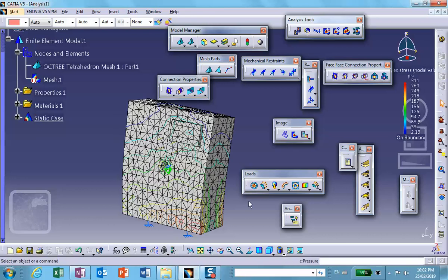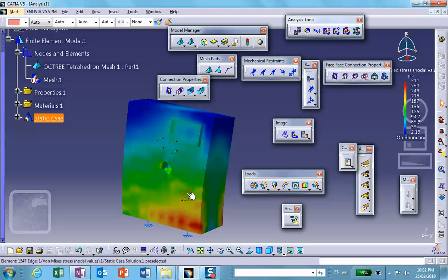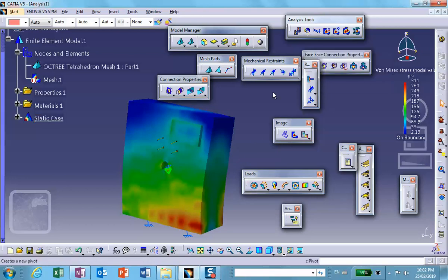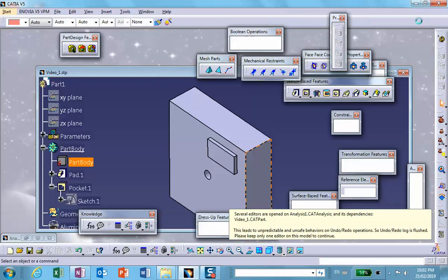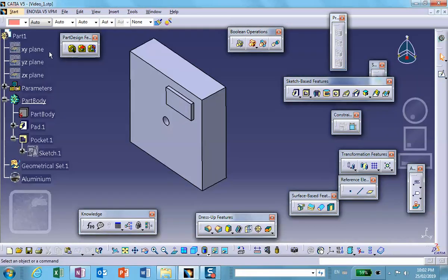If you assume that the mesh was satisfactory, then this is the stress distribution in that part. Now this mesh is horrible because this patchiness shows you that the mesh is not fine enough, but that was not the real issue. I wanted to remind you why we did this, because somebody sent us a dump solid, and we wanted to make some modifications in it.